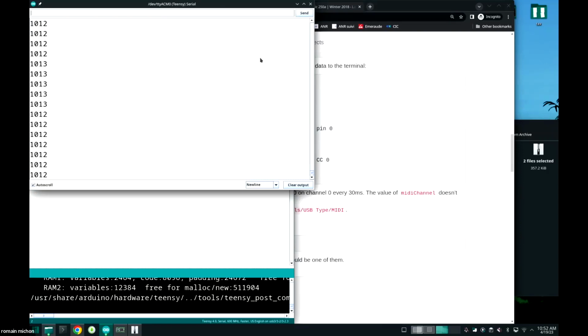Well, it's pretty straightforward. I'm going to use what we call a pull-down resistor, okay? So I'm going to use a resistor here, which is going to be my 10K resistor, and I'm going to connect the 10K resistor to the ground, okay? So what this is going to do practically is that, well, it's going to change the resistance of the FSR, but it's also going to sort of suck all the remaining electrons in this wire if I'm not pressing